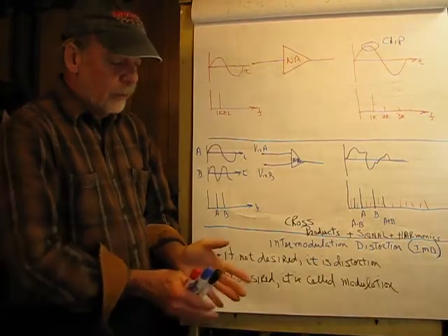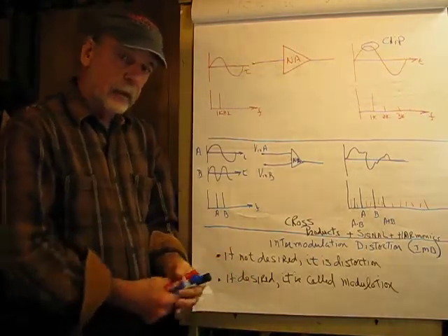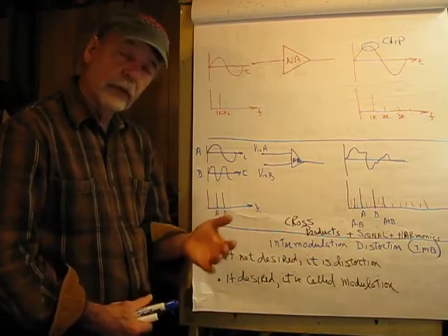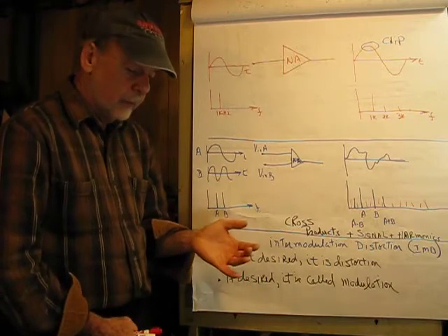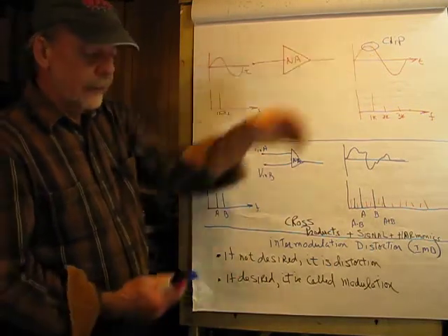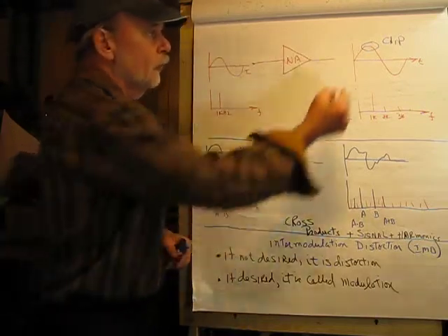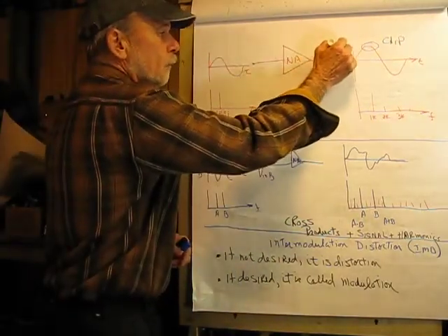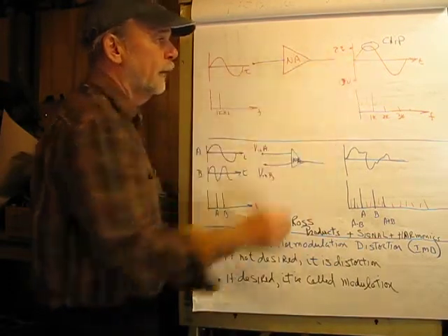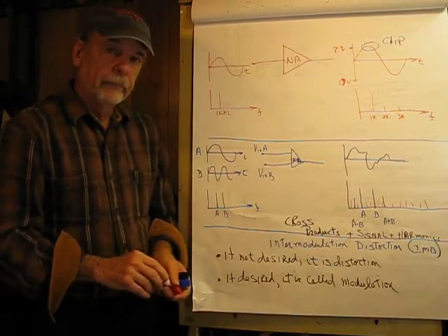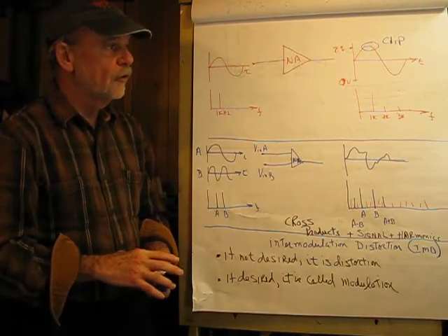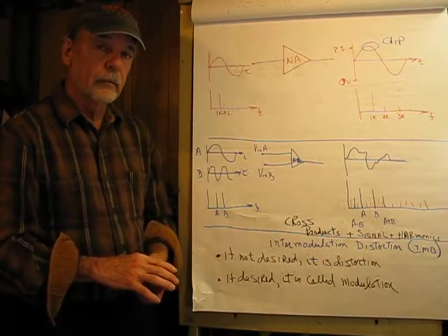So these op amps that I speak to in here are called rail-to-rail. They're CMOS, and they're a later technology, and they're also more expensive. But if we hit a supply rail, well, we can't go any higher, really. If we call this here 2.8 volts, and this down here would be 0 volts, should have centered that better, we're going to get a clip. Now, what that clip does is it converts the sine wave from something that's pure into something that isn't.